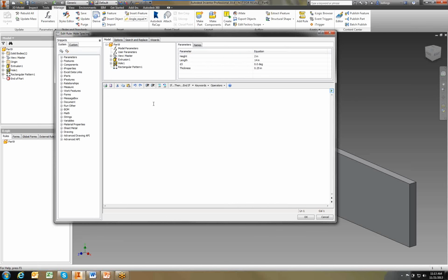What I'm going to start off with is that iLogic has some built-in functionality for us. The code is, in some ways, little templates, you might say. So what I'm going to start out with is an if, then, end if statement in programming. When I click on this, you can see what happens: it says if my expression then, and then an end if.